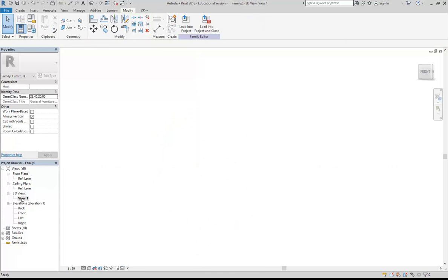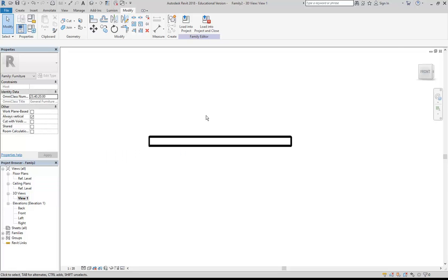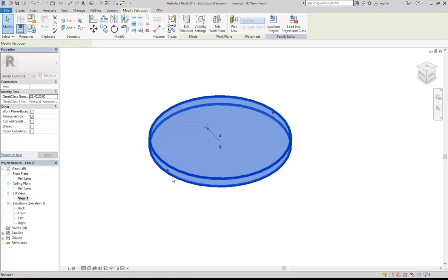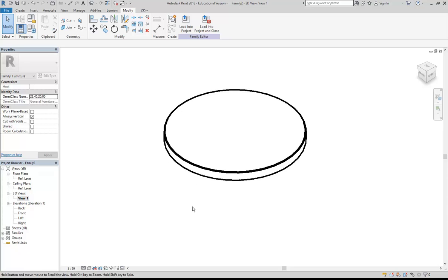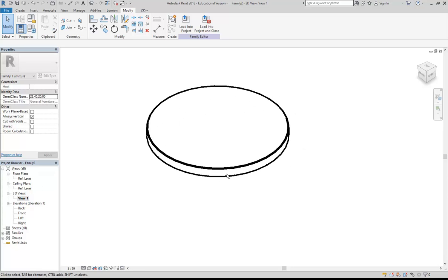and to see it in 3D, I'll go to my 3D view, and it's showing me nothing, which just means that it's looking somewhere else. So whenever you see something like that, you can just right-click and go to Zoom to Fit, and it'll find everything you've made. And it's going to orbit there, so I can see my table properly, or a tabletop. And so then I'm going to use some of the other modelling tools to make my leg and the other parts that I need.